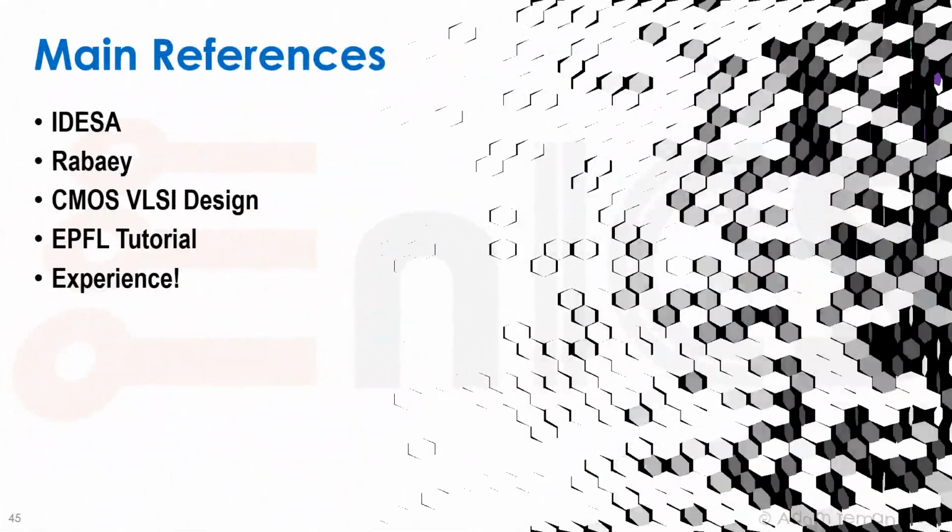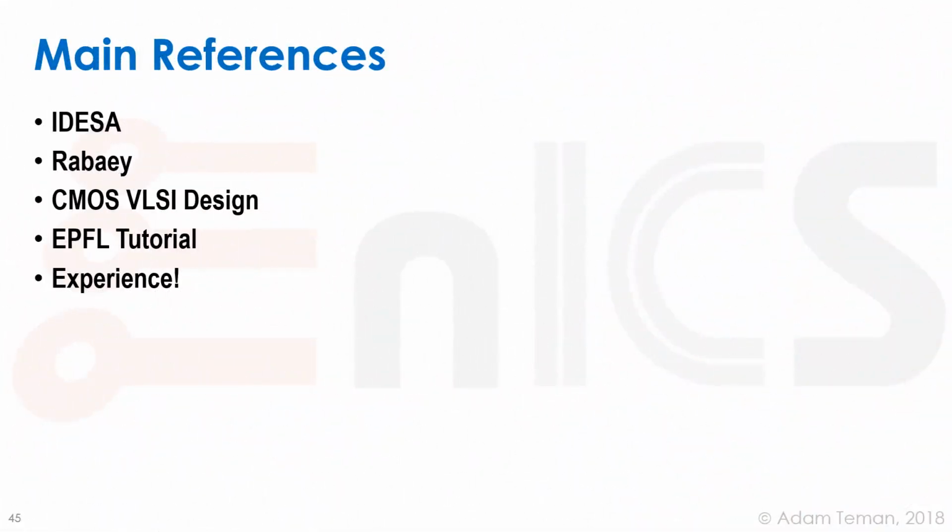So that's it for our discussion of floor plan. It was a higher level type of lecture, but it's really something you have to gain experience from. You have to do a lot of trial and error, see how our routing congestion becomes, see how our placement comes out, what kind of timing we can get. And this is something you'll have to go through many times. Floor planning usually takes up a large part of the design time of a back-end designer.